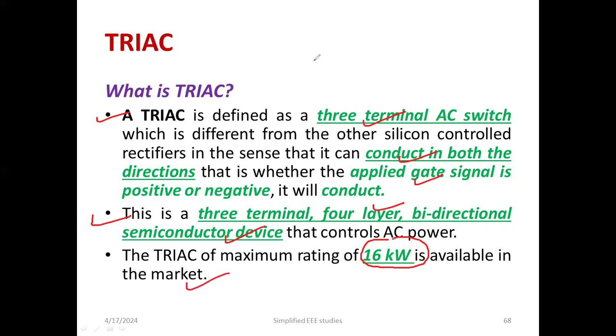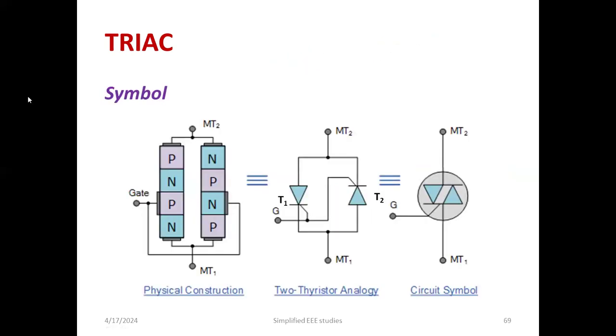So have you ever seen TRIAC? Yes, in your fan regulator. Or also we can control the universal motor, as in a mixer grinder, by using TRIAC. The AC voltage controller is a major application, also the light dimmer. So there are so many applications of TRIAC, so it is more attractive. Also, the requirement of heat sink is less compared to individual SCRs. That is another plus point.